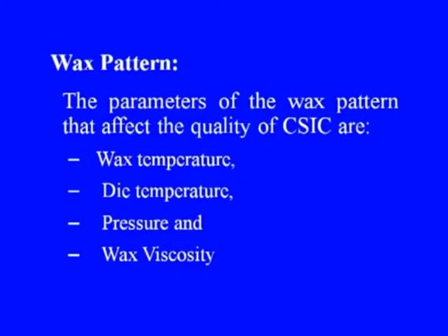This diagram depicts that the parameters are quality based parameters, which affect dimensional accuracy, surface roughness, mechanical and metallurgical properties. The wax patterns. The parameters of the wax pattern that affect the quality of ceramic shell investment casting are wax temperature, die temperature, pressure and wax viscosity of course.